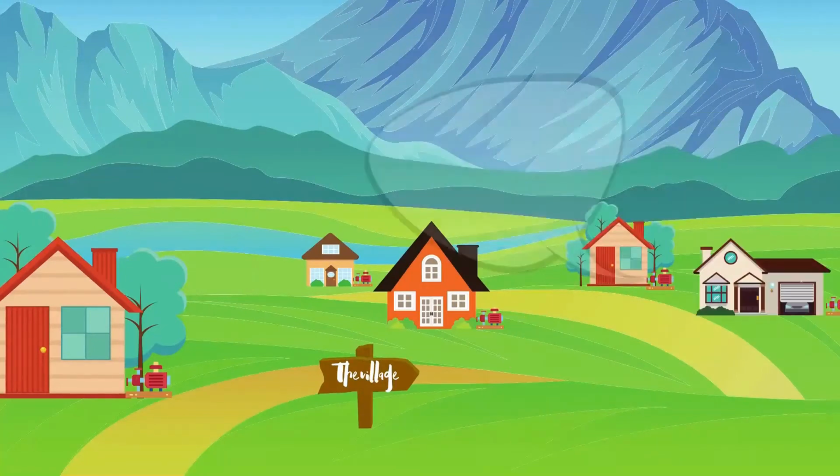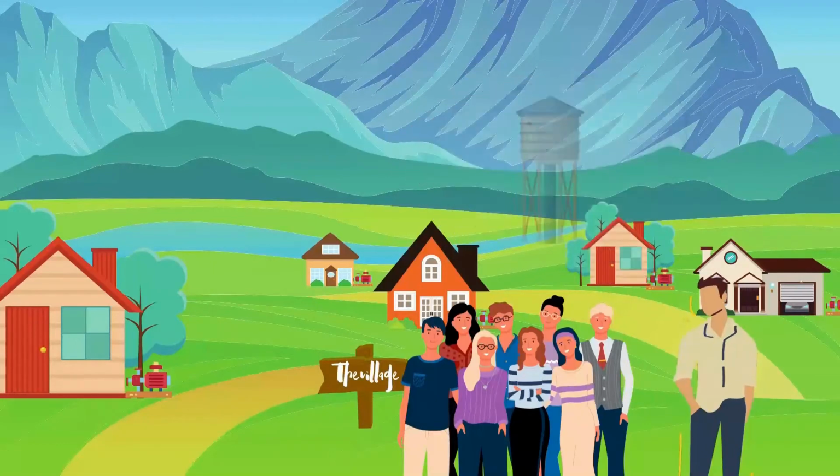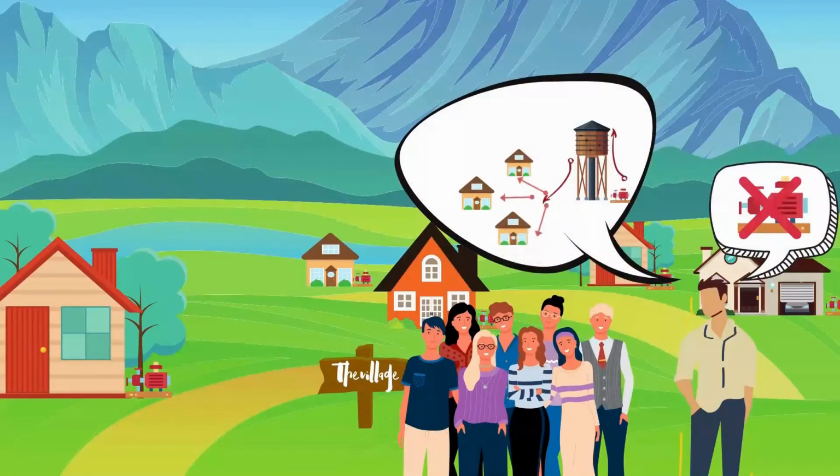So, the engineer decides to make a change and asks the villagers to help him build a huge water tower tank that stands high above ground level. The engineer explains that the hydrostatic pressure from the top of the tower is enough to carry water to each home, only powered by a single water pump to pump the water from the river into the tower water reservoir.